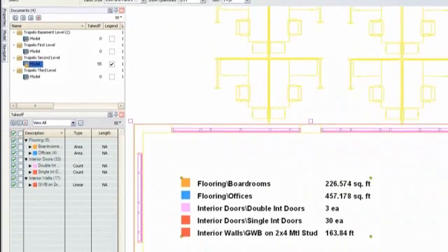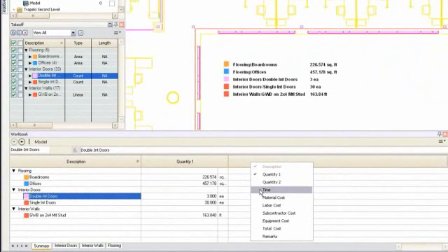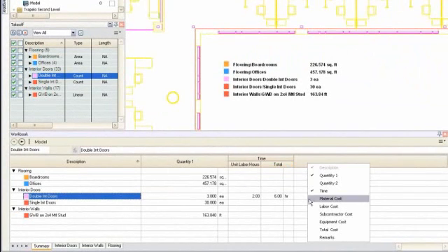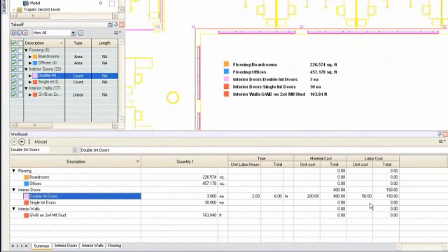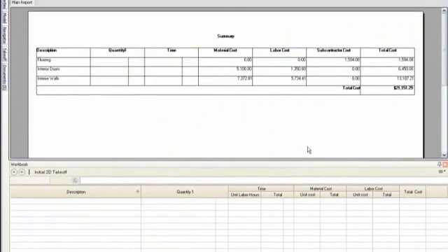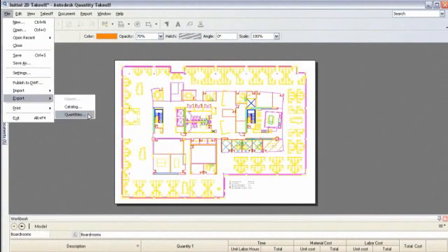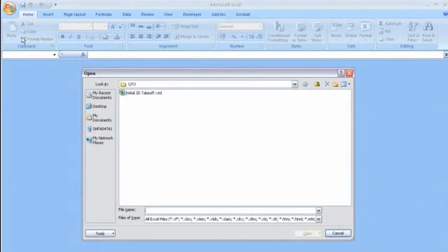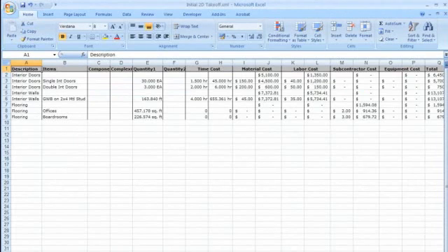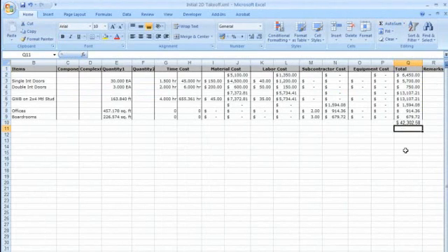While carrying out the quantification, the workbook is also being built out, providing another view of the building components. The workbook allows you to add initial cost information against each takeoff group, including material and labor costs or flat fee subcontractor costs as and when they're available. Reports can be generated directly from Autodesk QTO, and quantities can be exported to Microsoft Excel.